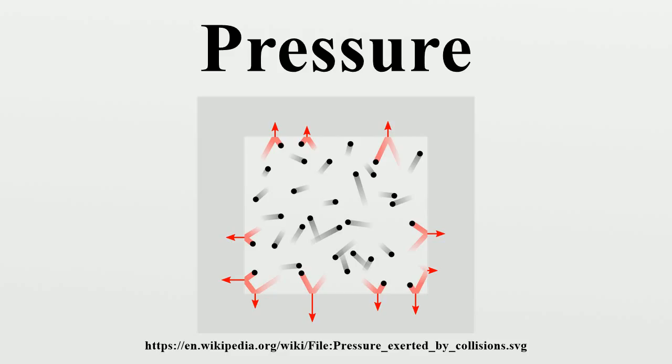Similarly, the pound-force per square inch is the traditional unit of pressure in the imperial and US customary systems. Pressure may also be expressed in terms of standard atmospheric pressure. The atmosphere is equal to this pressure, and the torr is defined as 1/760th of this. Manometric units such as the centimeter of water, millimeter of mercury, and inch of mercury are used to express pressures in terms of the height of a column of a particular fluid in a manometer.